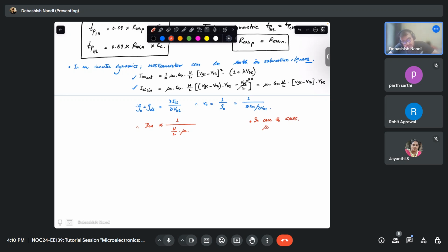Your mu N is almost twice of mu P. So that means you have to have your WP by LP twice of WN by LN. One problem we had solved in our last tutorial session.